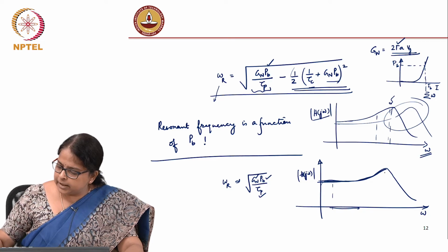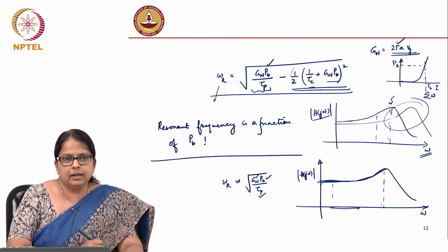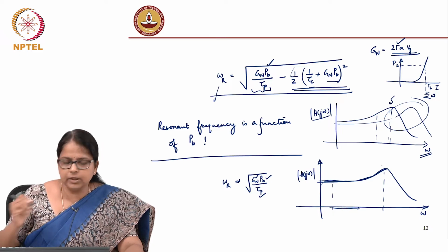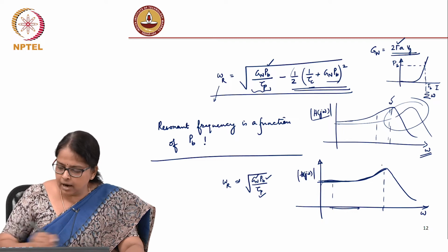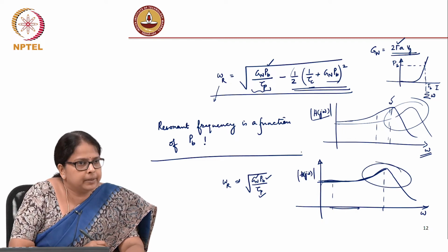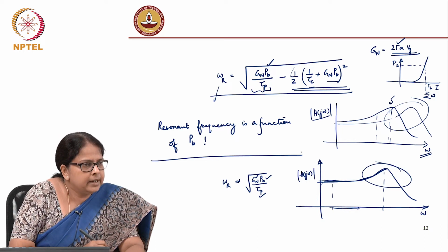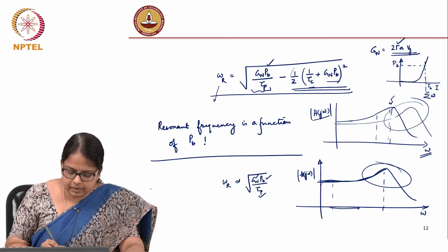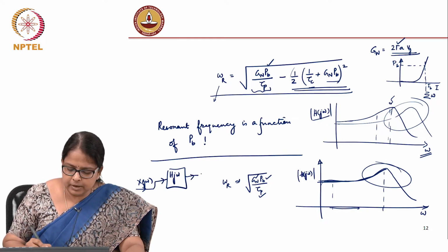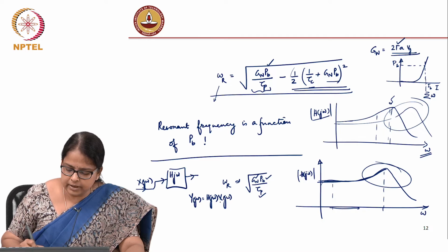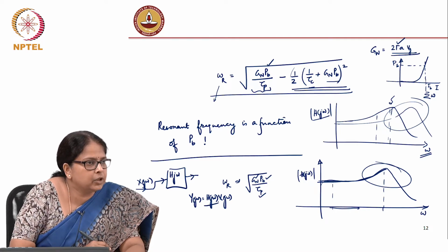But if my modulating current is operating at a frequency which is closer to the resonant frequency, the output is now a nonlinear function of the input, right. In the Fourier domain, your input is x of j omega, the system response is h of j omega, right. The output y of j omega is equal to h of j omega times x of j omega. We already calculated what the x of j omega and h of j omega are.